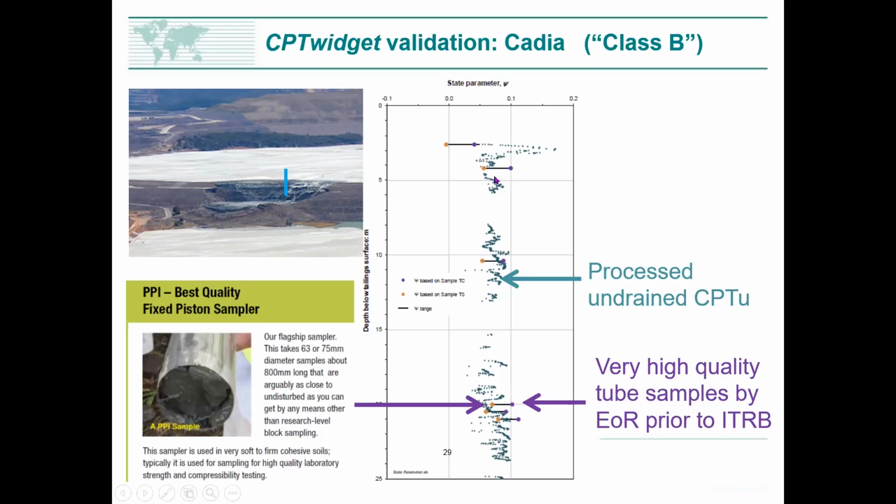Because what we as a board had also done is look at these tailings, and we said there's a predominant type of tailings and some sandier interlayers. And we determined the CSL of both of those materials. We could then say, well, if I know the density of the tube, I can turn that into a void ratio because I know what Gs is.